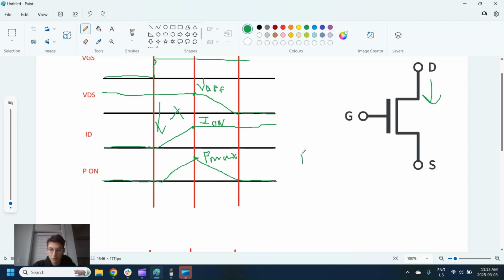What I'm saying is that the power for the switching on, because we switch off as well, right? So the power to switch on is just going to be, in this case, we're looking at the energy. So energy times the switching frequency. This is basically how many times is this happening? How many times are we turning it on? And that's the energy. And so this is going to give us our total power losses.